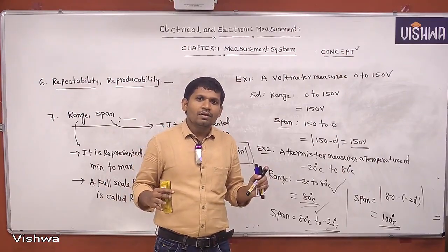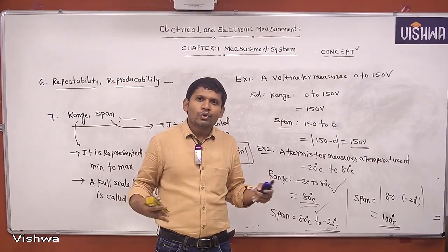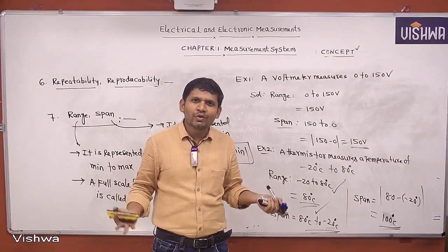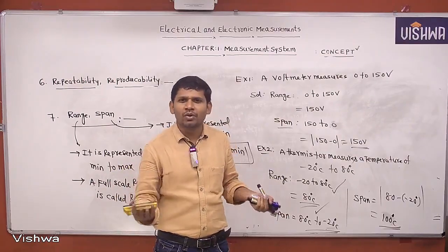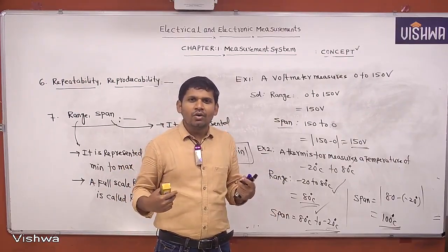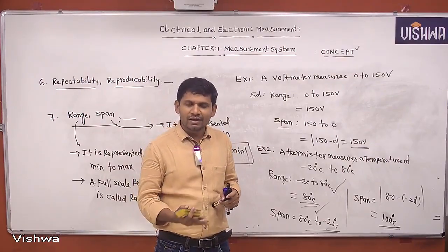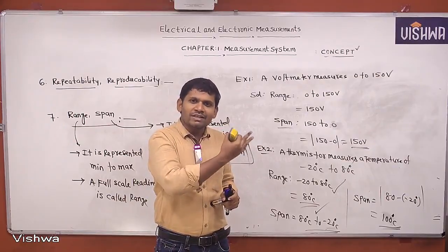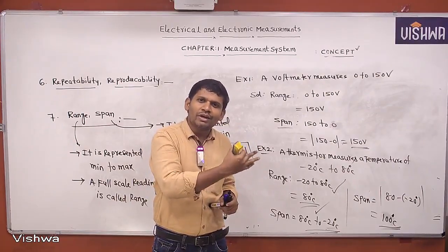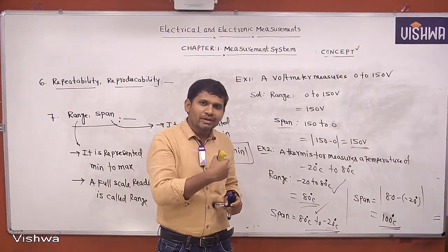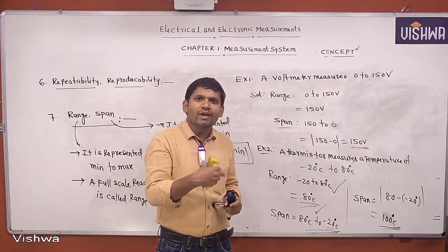But after design, due to usage, due to the instruments we are using, due to the materials we are using, we also get some undesirable characteristics. Now, what are those undesirable characteristics of an instrument? That I want to discuss. I will list them out now: hysteresis of an instrument, dead zone, dead time, threshold of an instrument, drift of an instrument, and static error of an instrument.